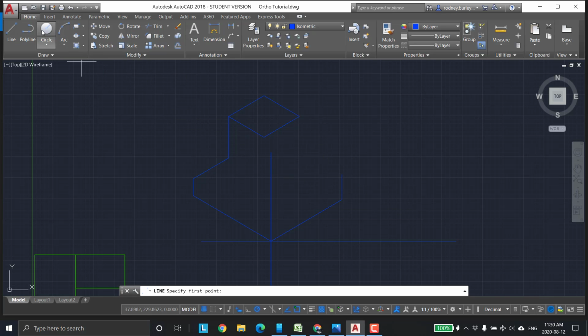So I'm going to go in here, and I'm going to go from here to here, and it's 150, backspace, 20, tab, 150, and you can look down and see the angle right there, so you can see where you're close. So 150, tab, right? And then we're going to come down, straight down 5 millimeters. I'm going to close this one off.